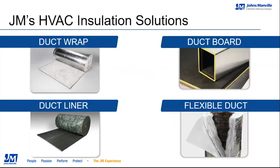So, Johns Manville's HVAC insulation solutions. We have 4 types of products offered, and I'm going to start in the top left-hand corner with duct wrap. Duct wrap is a fiberglass blanket that is wrapped around the outside of a sheet metal duct or plenum. The top right-hand side is what we call our micro-layer duct board. Duct board is a flat 4x10 sheet with special tooling that you use, upon fabrication and installation, to create grooves in the material. You bring the board together from a flat sheet into a square or rectangular duct. You seal the seam, and you get a completely closed and sealed system that has a vapor barrier, acoustical control, and a product that's kind of an all-in-one system.